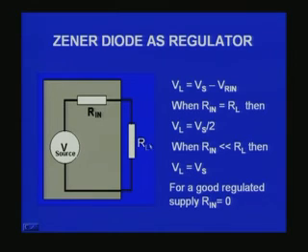If RL is infinity, that means there is no load, the load being absent here, it is an open circuit. Here you would find there is no current flowing, and therefore there is no voltage drop across Rin, and therefore whatever you get will be the total voltage source voltage that you have. So Vs will be measured between these two terminals.